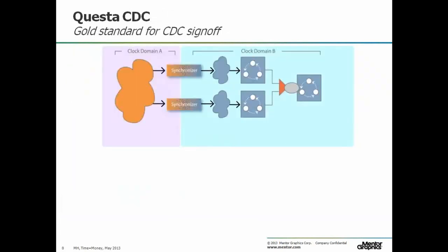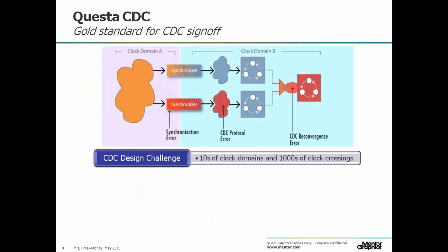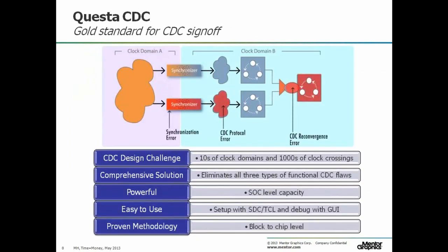Clock domain crossings, or the absence, guarantee the absence of metastability effects. Again, a formal technique can be applied in CDC analysis. So in CDC, there's typically three areas of concern. One is synchronized design. So here you can use a formal tool to analyze RTL, to find all the CDC paths and check you have synchronization in all the right places, and that synchronization has been defined and designed correctly. So there are structural-based rules for synchronized design. So you can use the formal tool to not only check for presence or absence of synchronizers, but also structural design correctness too.